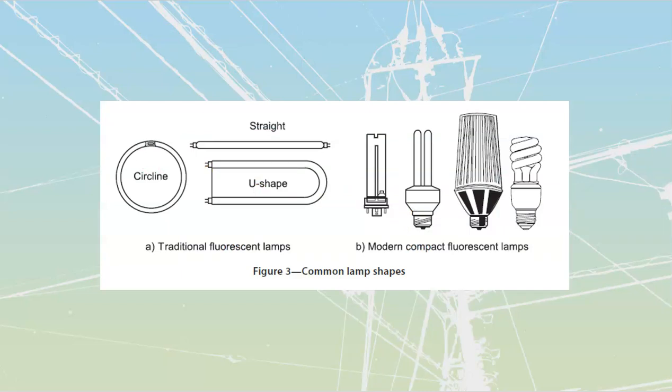Looking at bulb shapes, we should be very familiar with these ones here, the straight bulb shapes. We're going to have different ends on them. There are U-shaped ones that are generally seen inside of 2x2 troffer fixtures. If you've worked in the industry and commercial at all, you would be familiar with the concept of troffers. Troffers are those fluorescent fixtures or LED fixtures that you drop into a T-bar ceiling. Oftentimes, the U-shaped ones would then allow you to use the same 4-foot ballast, and they would just have a 2x2 grid, and they've got that bent out U-shaped bulb inside there.